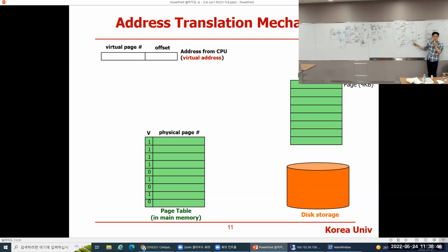The name is very intuitive: translation table base register. This is a base location. That should be programmed to indicate the start location of the page table. So every time task switching happens, the operating system is updating this TTBR register to point to the new location, let's say the page table for T3. So like this.